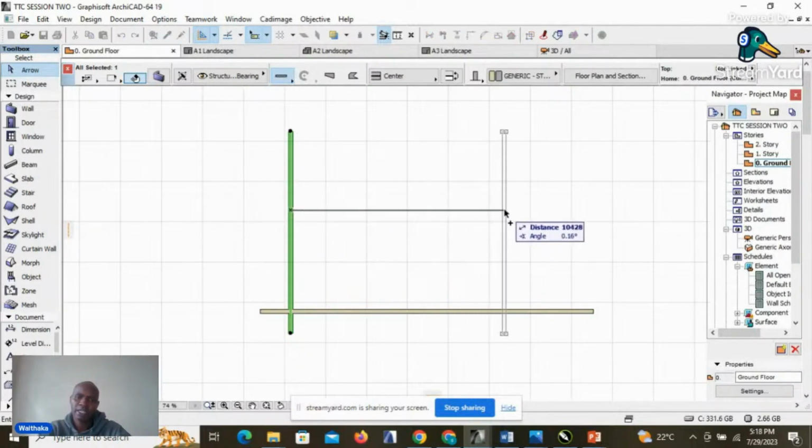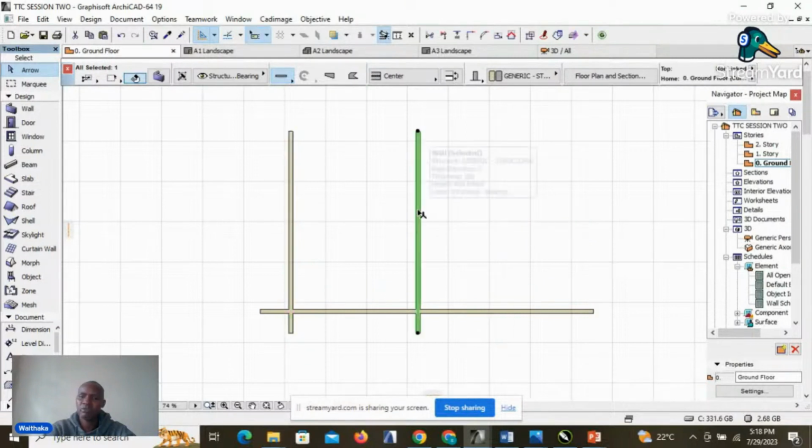We will drag that copy to a new position, displace the cursor, then we enter the command for entering dimension, that is Shift+R, and then we put 6200. Remember, we said we have to add the thickness of the wall so that to achieve an internal dimension of 6,000, and then we press enter from our keyboard.